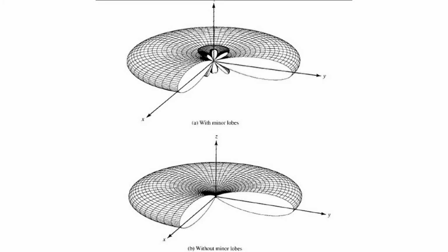See, this is the omnidirectional pattern. You know the omnidirectional pattern has directional properties in one direction and non-directional properties in another direction. That non-directional may be isotropic also. If you say the pattern in this direction, that is the phi direction, it is actually isotropic, and in the theta direction, these are all directional patterns.